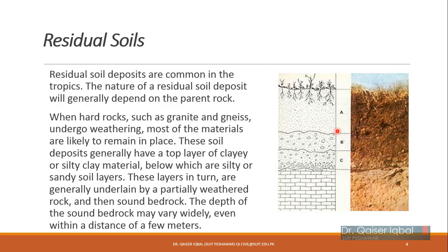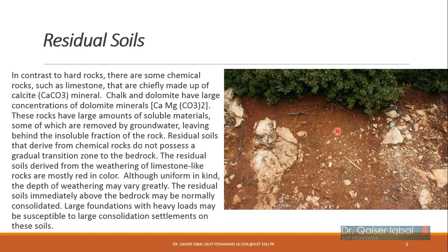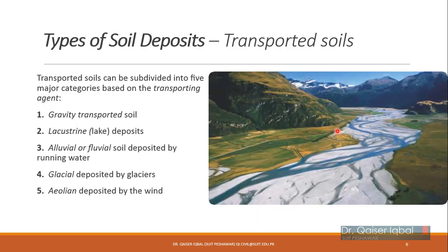You see, these residual soils which result from hard rock will usually be of better strength, and they will have more settlement resistance compared to residual soils which are derived from soft rock like calcite, calcium, magnesium carbonate, etc. Okay, so now moving on to the transported soils.